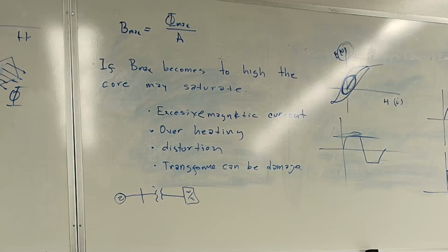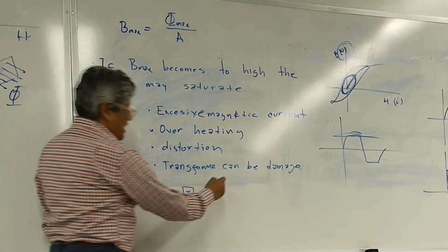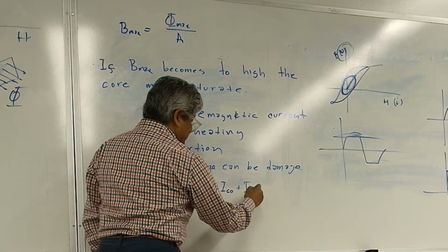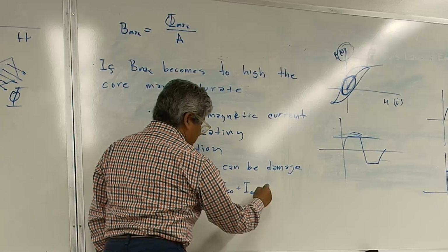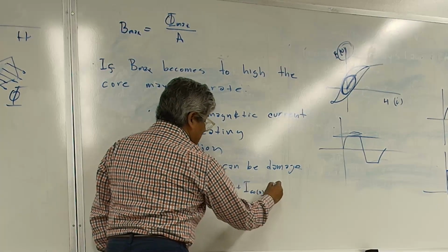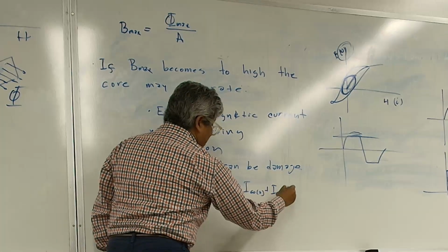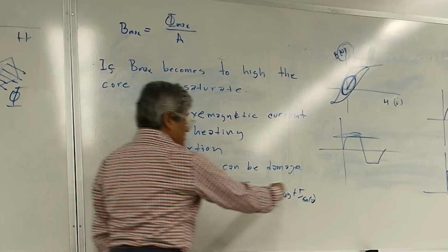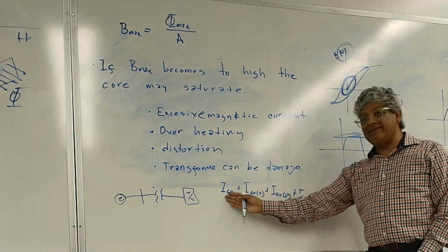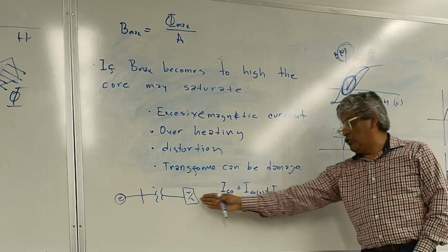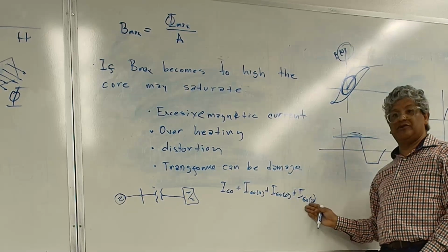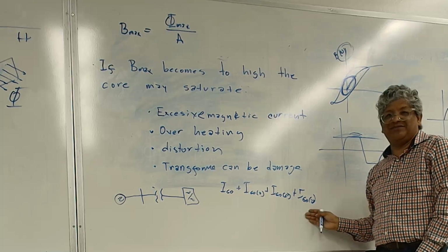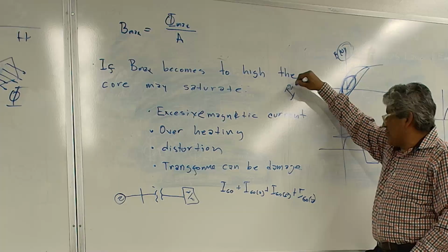And the problem with that is that, remember, the harmonics is this: I fundamental plus I 60 times 3. I'm going to use odd harmonics, not even. I 60 times 5, I 60 times 7. I can continue on into this. You have 60 hertz, the load is asking for that, but it's also asking for all of these other harmonics. These are currents. Current is current. It doesn't matter what frequency, it's still I squared R losses.